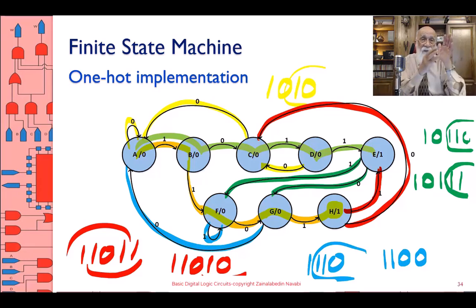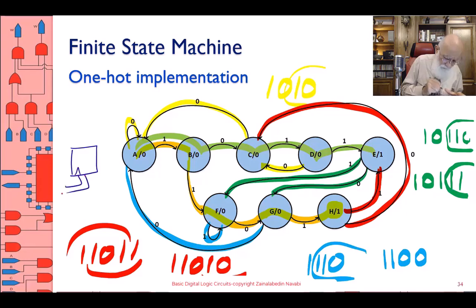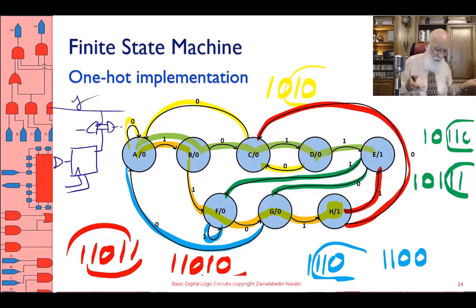What I'm going to do is I'm going to take a flip-flop with 2 AND gates here. Without getting there, I'm going to show you this. I'm going to take a flip-flop with set and reset. I'm going to put an OR gate on the side of it. I'm going to put 2 AND gates on the top of it, and then connect this to my J input, and then I'm going to repeat this 8 times.